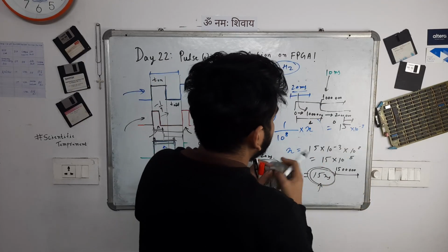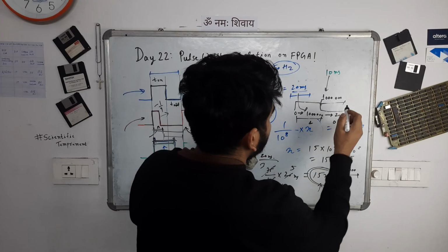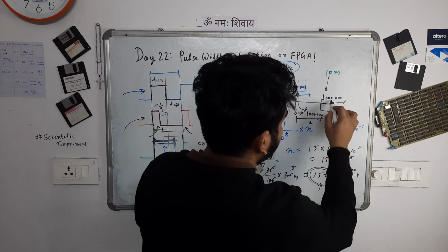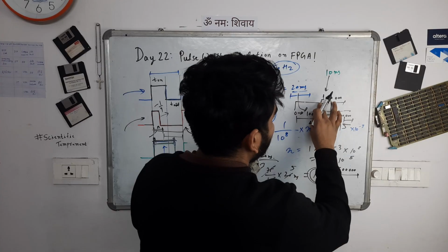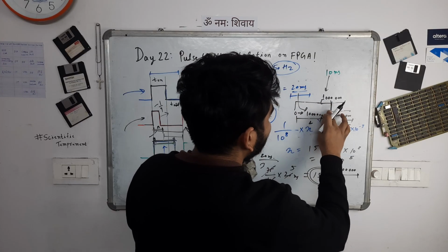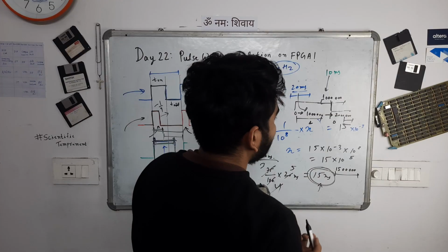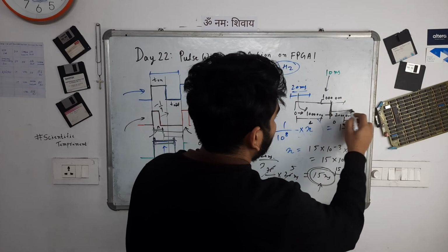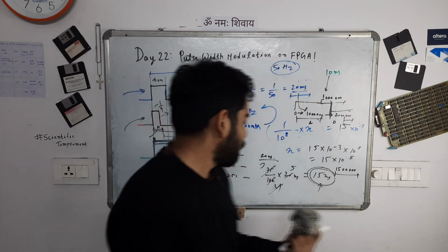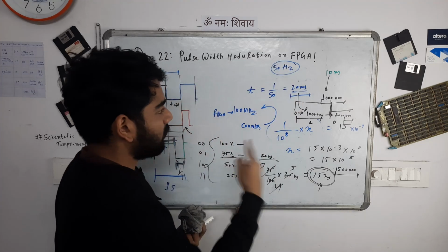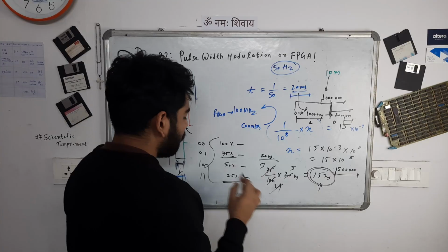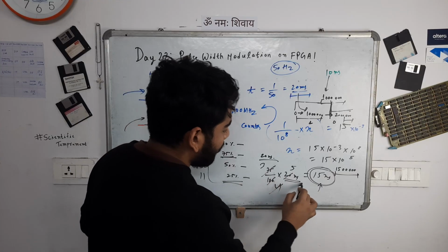Okay, so if the counter reaches 1.5 million, over here, going from 1 million to 2 million, we will have 1.5 million as well, right? So we will have the output set high until the counter reaches up to 1.5 million, and then we'll have a 75% duty cycle. Okay, this is the logic. Similarly for 50%, we have already seen, we need 1 million. If we calculate for 25%, you can again calculate for how much time it is high.